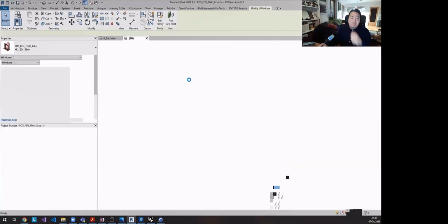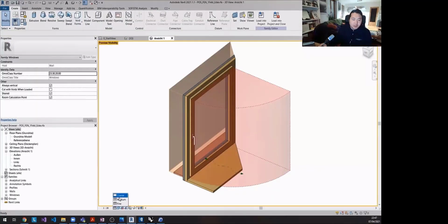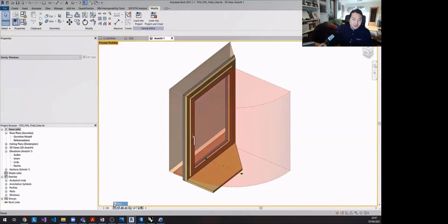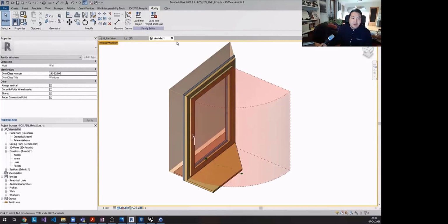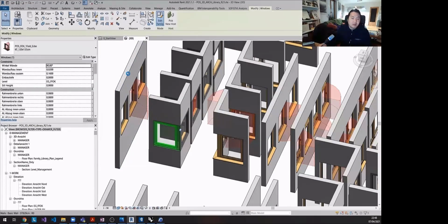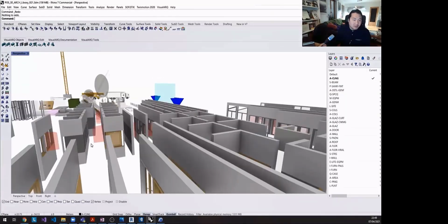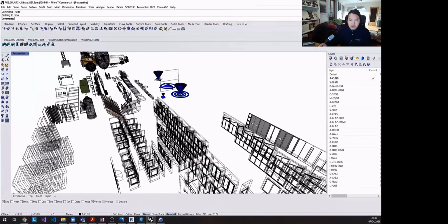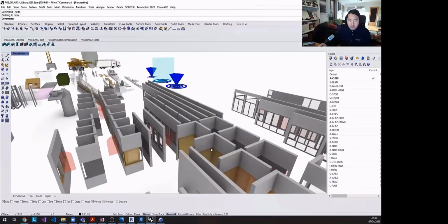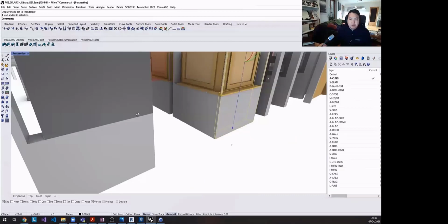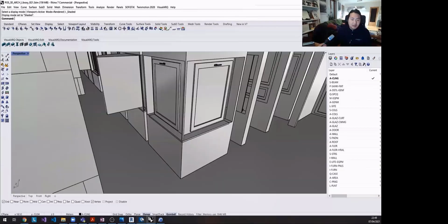And if you look at the detail, we have coarse detail elements that can be visible, and medium and fine detail. The problem is, even though we set these coarse detail elements, they are not exported as IFC. And when you open or import in different applications, unfortunately this is still appearing, or the corner where it's supposed to be cut is not a perfectly cut geometry.